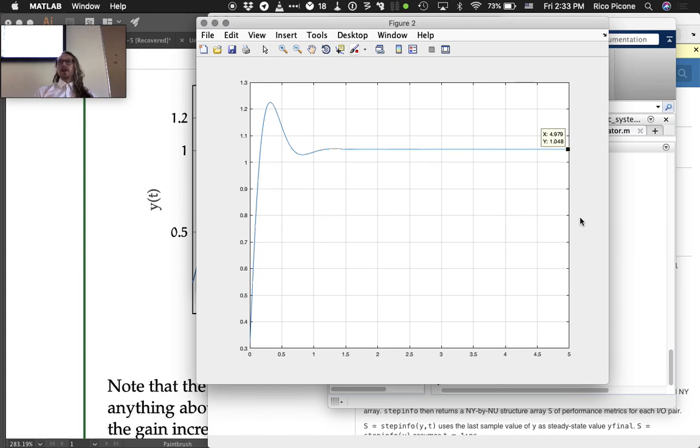If we incorporate an integrator in, if we have a 1 over S term in our controller, we're going to be able to get that steady state error down to 0. But including an extra pole in our open loop transfer function, and therefore our root locus, messes with everything to do with the transient response. Like everything changes. The entire root locus changes. So what we're going to do next week when we learn how to do PI control, proportional integral control, is we'll learn how to mitigate the effects on the transient response of putting in an integrator. So we'll talk more about that next week.